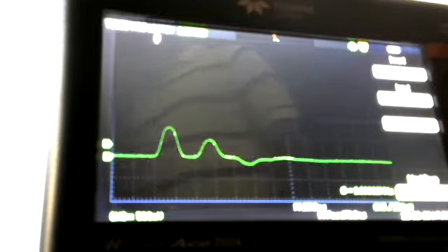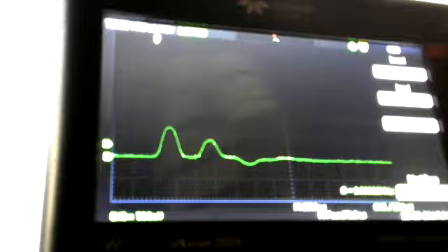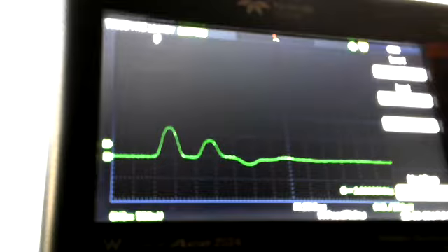Okay. So pay attention to the distance between the pulses because that is determined by the length of this cable. And this is that bad cable which doesn't have any connector, but it's still like an open end. I'm going to attempt to damage this cable somewhere in the middle and see if I can make it reflect.